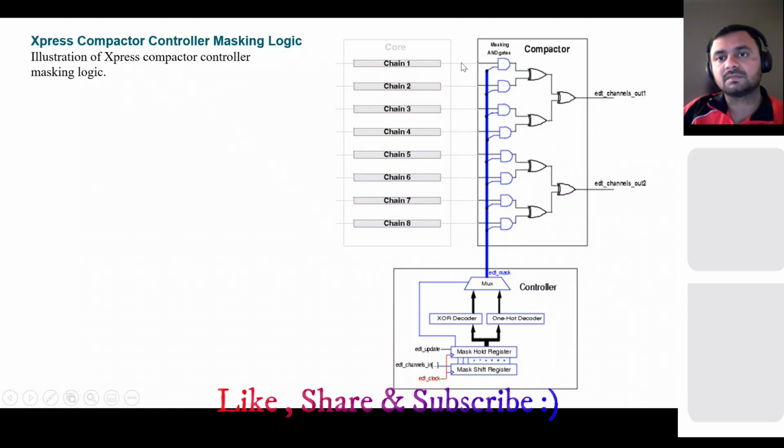As I told, in the AND gate one input will come from the chains and the other will come from this mask register, and that will generate a 0 for the particular chain based on your requirements, which channel you want to mask. That particular channel pattern will be saved here, and this decoder will select those particular chains, so that you are not masking the other chains unnecessarily.